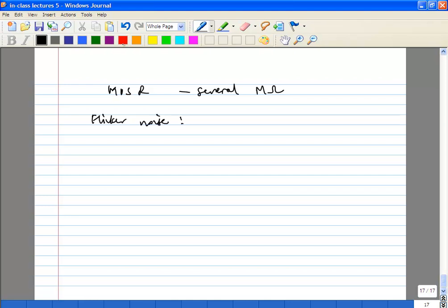And the other thing to remember is flicker noise. Remember that ideally your resistors are supposed to have only thermal noise. Okay, but many of these resistors, well, not many of them, some of them could potentially show flicker noise. Okay, because flicker noise inherently happens at interfaces between different materials, and when you rely on silicon based resistors, you naturally expect it won't be as high as MOSFETs or even bipolars, but there are some special cases where you could see flicker noise.